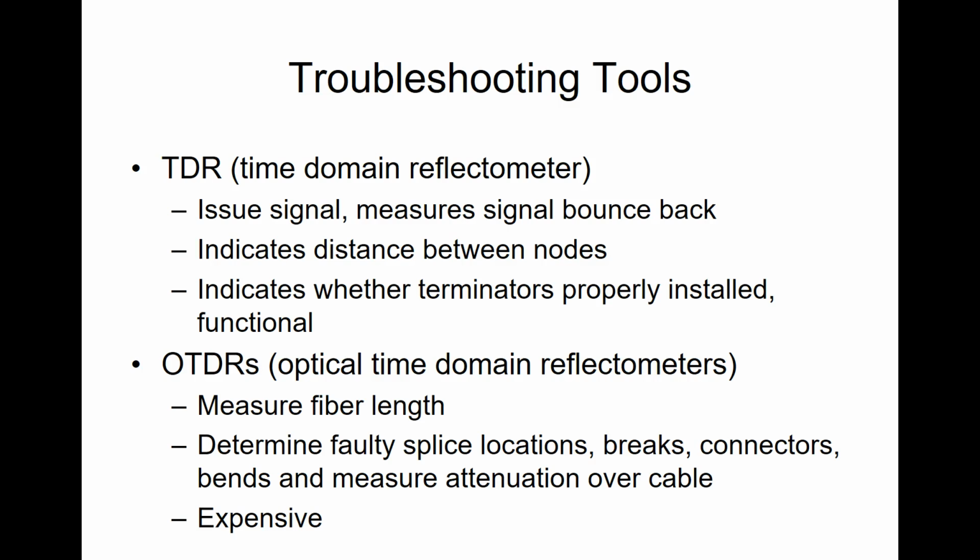Because fiber optic cable is traditionally fairly pricey, the outside plant cable that you see when they're putting in fiber for companies like Zayo, which just went through, or Qwest, or any of the big players, you're talking $8 to $10 a foot for that cable. They will actually use OTDRs and measure each reel of cable to get its characteristics. And then as they splice them together, they'll do one at the end to make sure it meets all of the specifications.